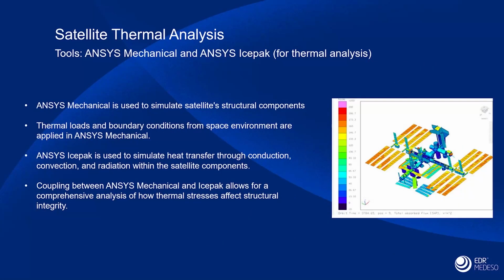Now, clearly in space, the structural response to thermal loading is going to be of key importance, and this functionality is one of the primary analysis methods available in Ansys Mechanical. So we can represent the thermal properties of the various materials, things like the expansion coefficient, or the conduction, convection and radiation coefficients and capabilities. We can investigate how those thermal loads and heat transfer will affect the structural performance of our systems.